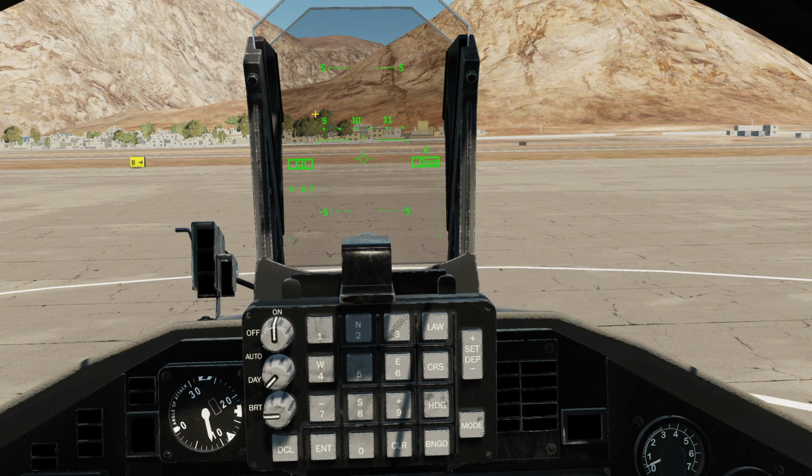A magnetic heading tape here, 090, 100, 110, and currently our indicator there, and we go through this thoroughly in the navigation tutorial. Our velocity vector here shows you where our aircraft is actually going at this point in time. Our indicated airspeed in knots, minimum 50. Our angle of attack, currently 8.7 degrees. In other modes we will have extra symbology here. Our current barometric altitude here, 80 feet. Our VSI here, vertical speed indicator, obviously 0 at the moment, will show us if we're climbing or diving.